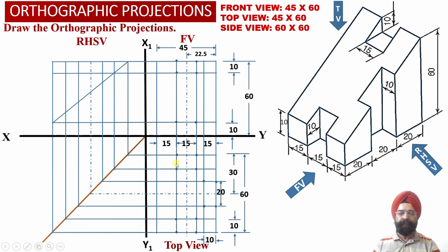So now we can check these 4 dots which are going to represent the rectangular true shape projections of this horizontal surface, which will be visible to the observer from the top view orientation over here. So this way one missing link, that is the depth of this horizontal slot, has been evaluated over here. Next we need to evaluate the height of this point from the ground. We need to evaluate the height of this point from the ground over here.